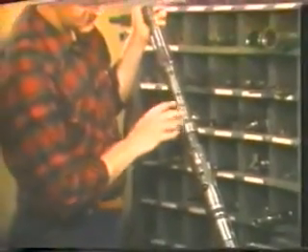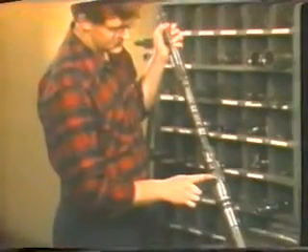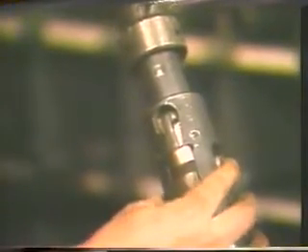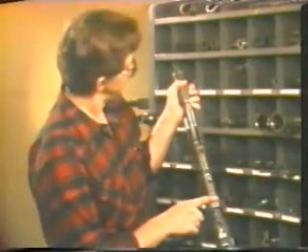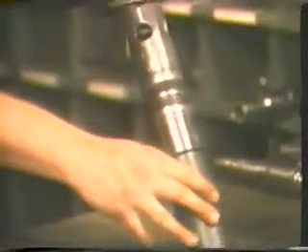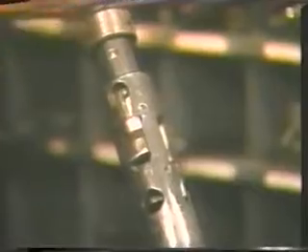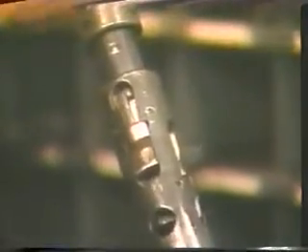Once pinned to the E running tool, the S-lock is run in the tubing with wireline. The lock passes through the tubing and nipples because the locks are held retracted by a plunger in the running tool. Once the nipple in which the lock is to be set is passed, the tools are pulled back to the nipple. As the running tool and lock assembly are pulled upward in the nipple, the locks on the lock assembly snap into the locking groove in the nipple.